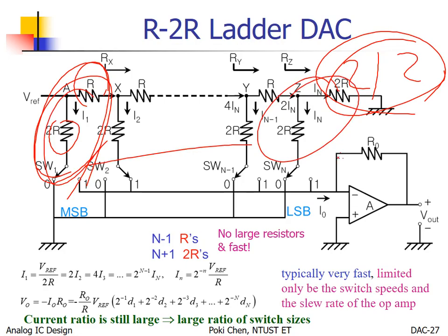Because again, in theory, everybody gets one 2R and one 1R. So after I do a very excellent layout pattern for 1R and 2R, then I duplicate the same layout for all the others. Right? That is the usual case. Not only in the past, even in the class, I think most of the students will do the same silly thing. But what is the problem?